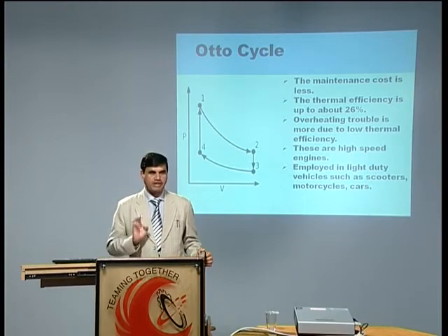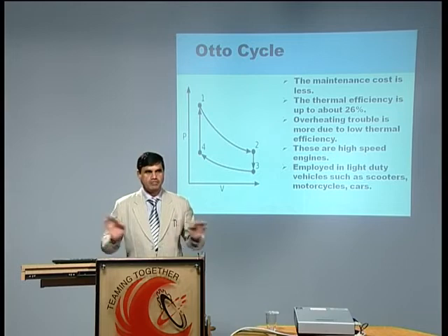I said peak temperatures in the case of a petrol engine are more, because combustion is faster. If peak temperatures are more, then overheating troubles are there. Even the life of the lubricating oil which we supply to the cylinder for the purpose of lubrication becomes lesser, because it has to sustain very high temperature. The lubricating properties of the oil will be destroyed due to the high temperature.